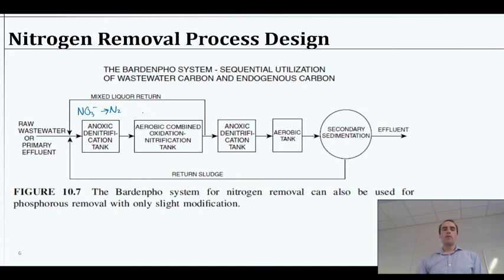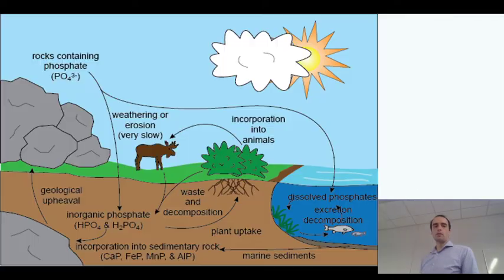So then we have the typical aerobic chamber where we've got NH3 going to more nitrate, followed by another sequence where we're going to do the same thing and ending with an aerobic tank. And that's probably preferable anyway. If you're going to discharge wastewater, you probably want it to be as full of oxygen as you can to avoid this whole BOD problem in the first place, right? So it's a sequenced situation, a little bit more advanced in terms of the biochemistry and some of that management, but that would be a common way to do it.